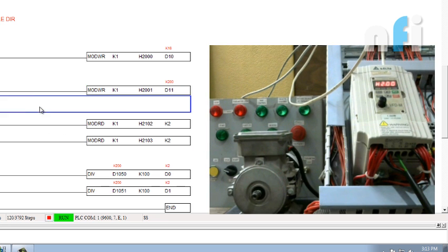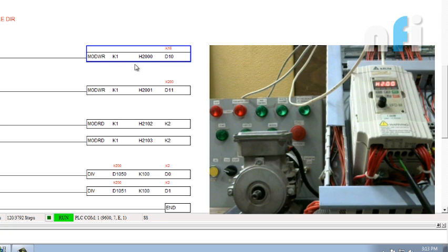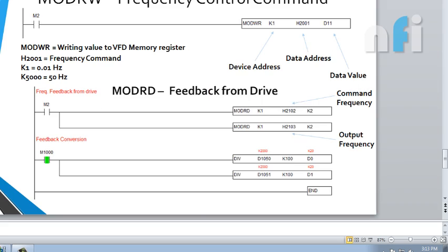So that was about Modbus communication. Our main registers are 2000 and 2001 to give the value, and you can even give the value using an HMI. Connect an HMI, take some pneumatic interrupt D10, D11, or you can take some buttons and you can move the value. So it will make it very easy to control the drive using an HMI just by 2 wires, RS485. That is the beauty of this Modbus communication.